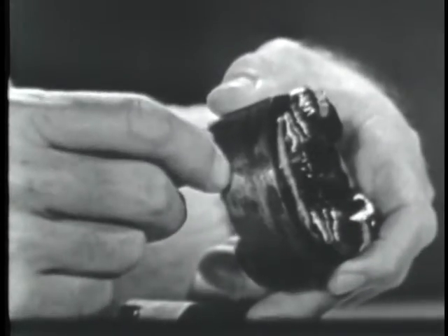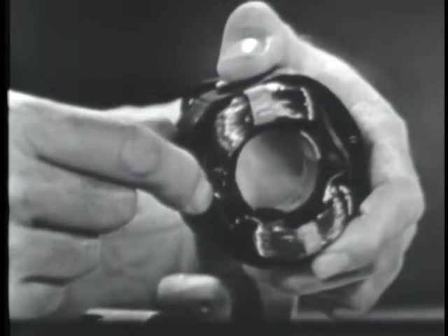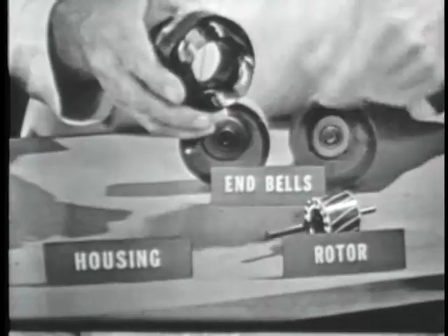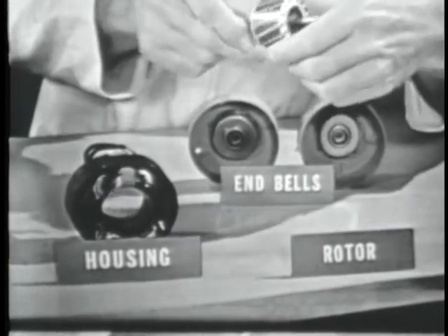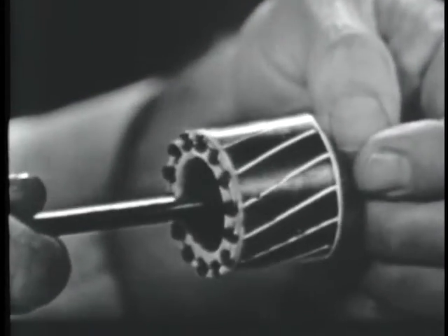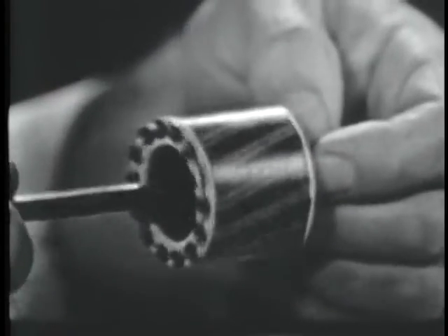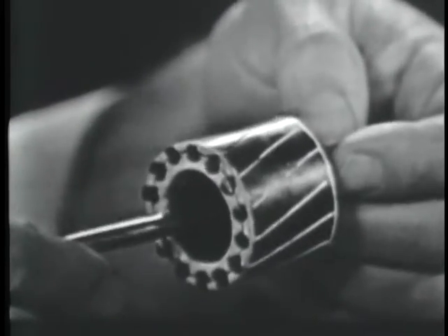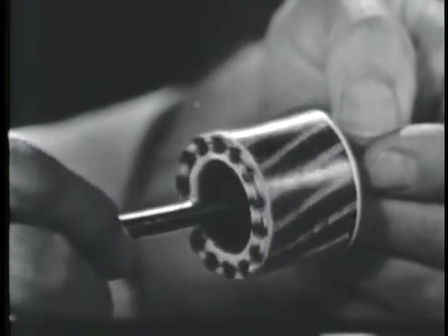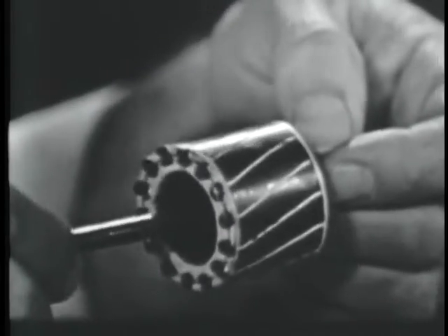Now notice the simplicity of construction. We have the stator field windings, the iron core. Very, very rugged and very simple. Inside the stator field windings, the rotor. Let's take a look at this rotor. All right, the rotor has no commutator, no slip rings, and no wire windings. It doesn't look at all like the rotor used in DC motors, does it? Not at all. Now, this particular rotor design is called the squirrel cage rotor because it resembles the exercise cages used for pet squirrels. And like the squirrel cage, the rotor is very simple to construct.